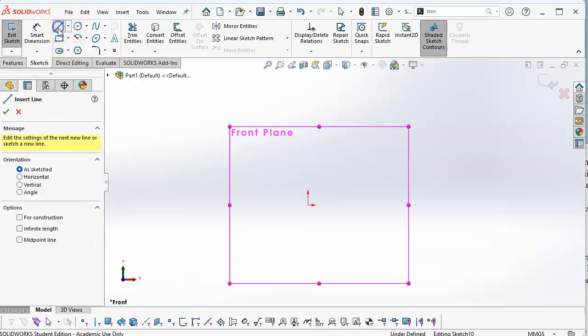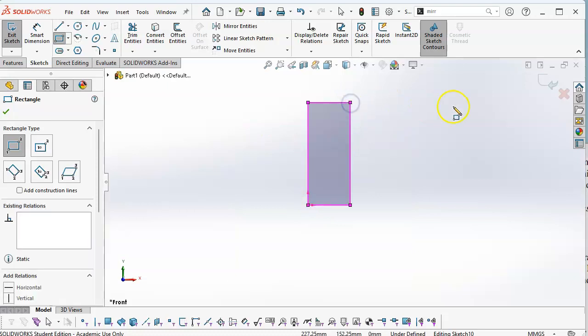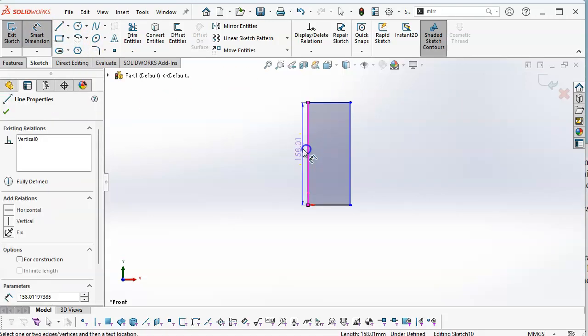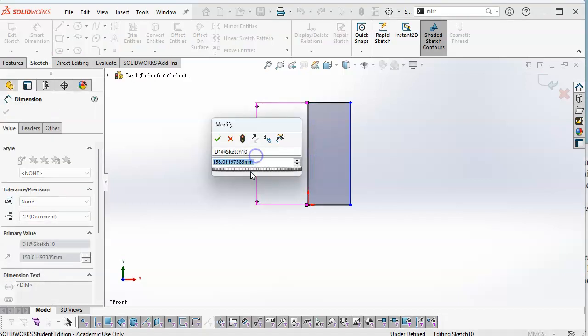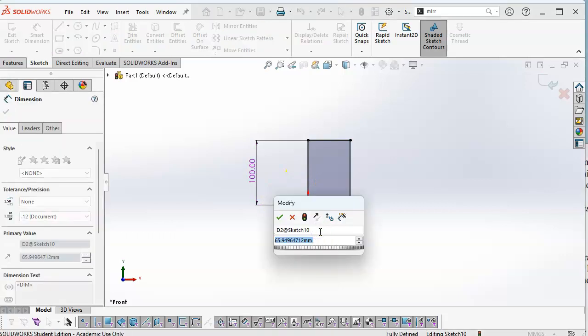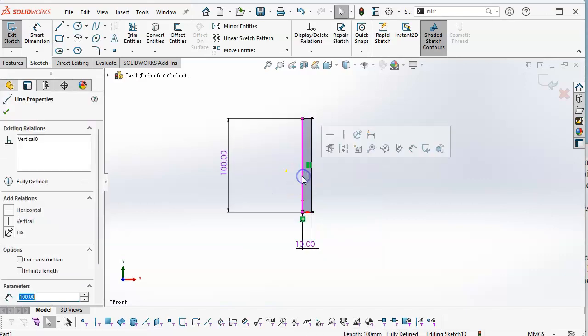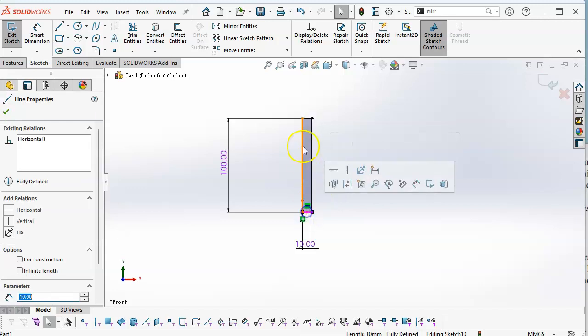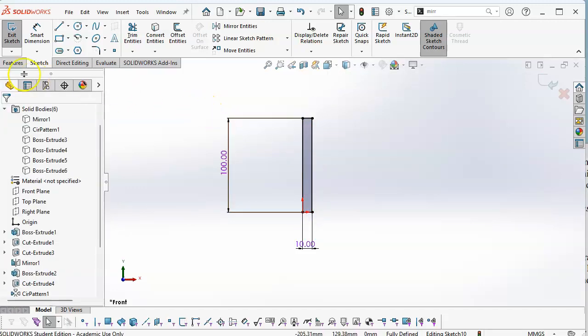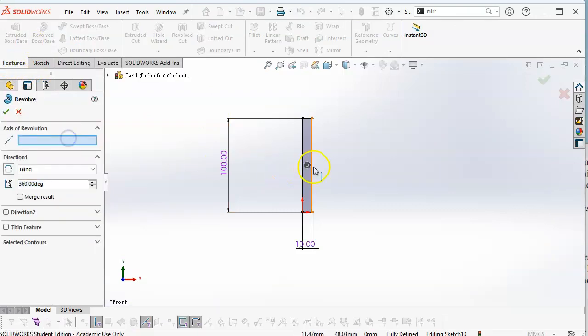So let's go ahead and do the rectangle. Opened up a sketch on the front plane. We'll do the rectangle. If I look at a part and I think, oh, I'm going to make this on a lathe, then it's probably going to be a revolve. All right, so 100 millimeters. I don't have anything to do the diameter, so I'm giving it a radial. Let's go 10. And I want to pick an axis. So these will not self-intersect when I go to revolve, so it doesn't really matter which one I pick, but it is going to affect the resulting geometry.